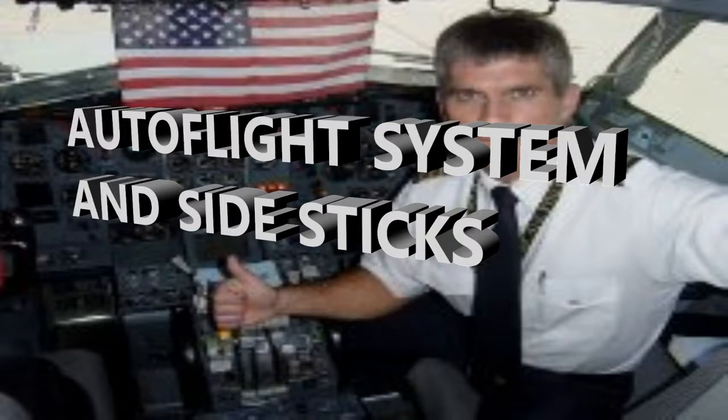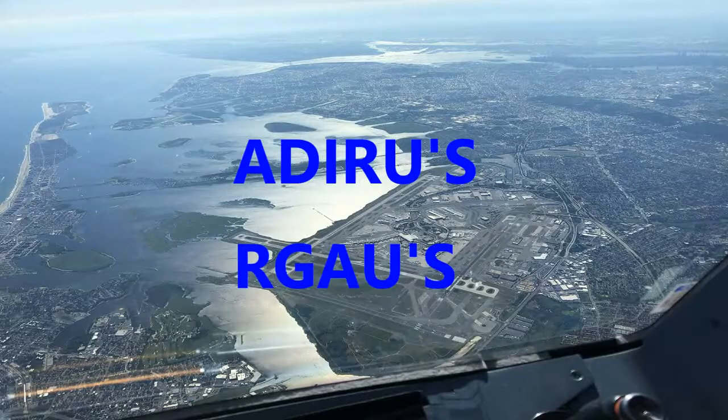At the same time that it's getting this input from your AFS, your auto flight system, or manual input, it's also getting data from the RGAUs, the rate gyro accelerometer units, for attitude data, etc., and inertial data. So it's getting all of that and computing the deflections for the ailerons as well as the spoilers.